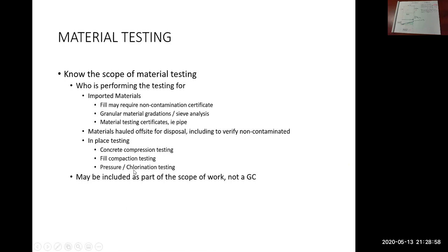This one is not materials testing, it's pipe testing. So pressure and chlorination testing. So that's a different company. That's when you are installing pipes. So specifically water main are pressure tested and chlorinated.